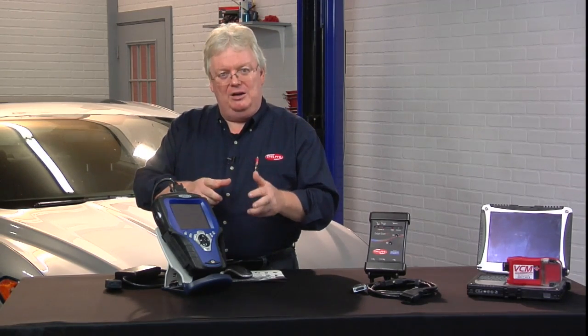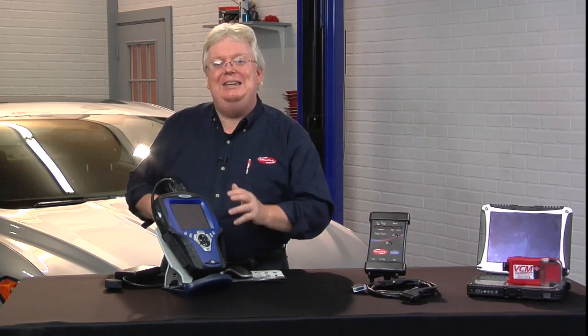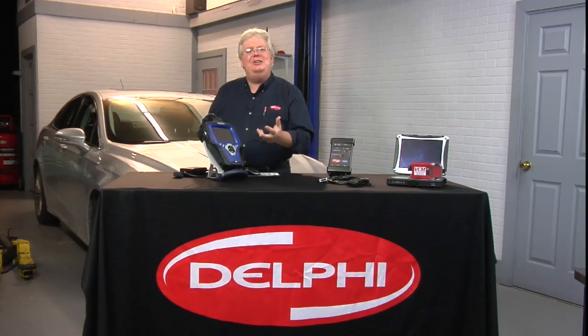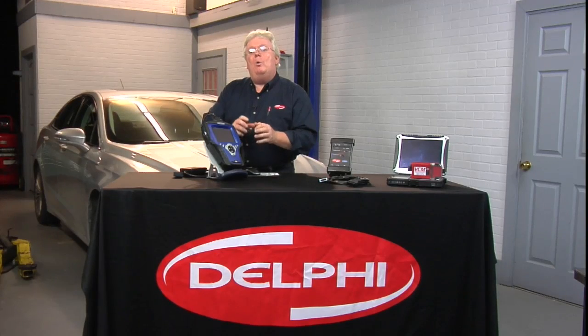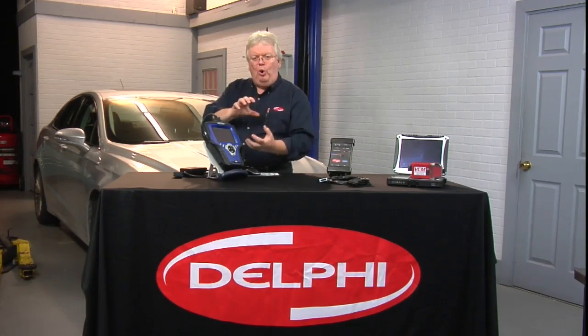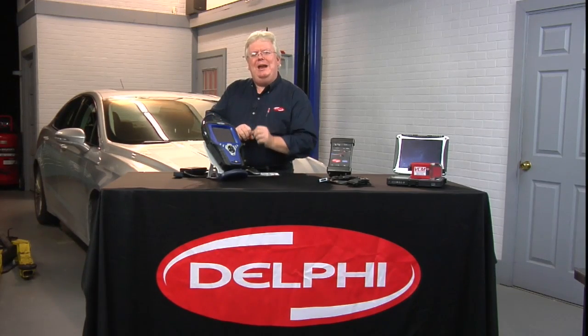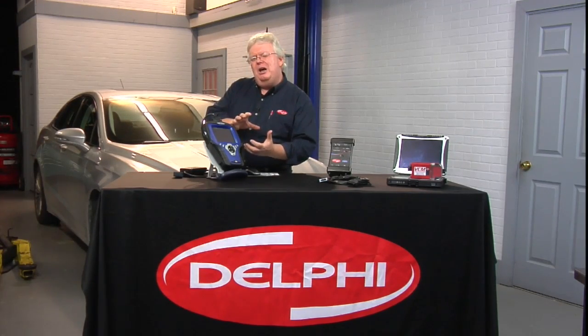Mode 6 will tell you how close you are in many cases on the non-continuous monitors. And there's two types, continuous and non-continuous, as we review a little bit of OBD2. But the non-continuous ones are what we're focusing on. That's what Mode 6 is about. When the monitor runs, we store some information when it ran last about what was going on, the details of